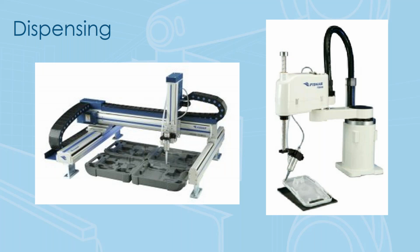In this case, we talked about the versatility of an articulated arm. They would also be well suited for dispensing because typically these aren't high-speed applications. So that's where, again, an articulated arm would work, but we typically see either Cartesian or SCARA robots used in this case for dispensing applications.